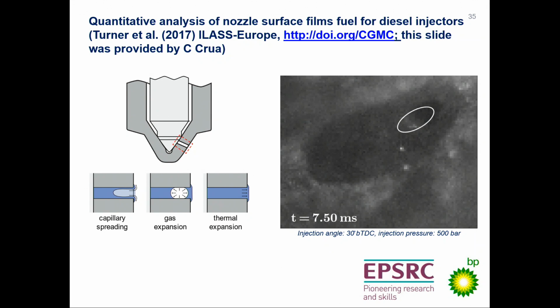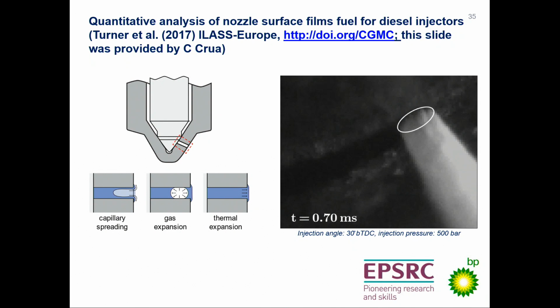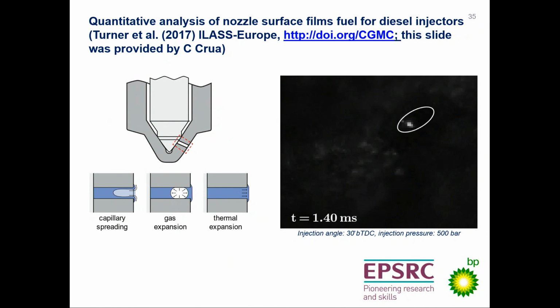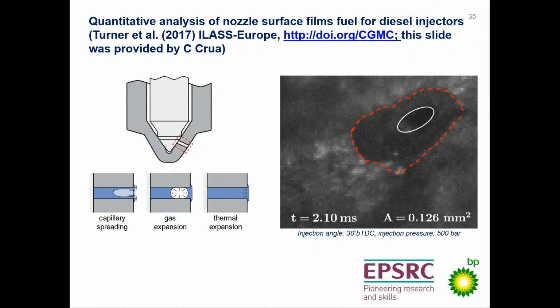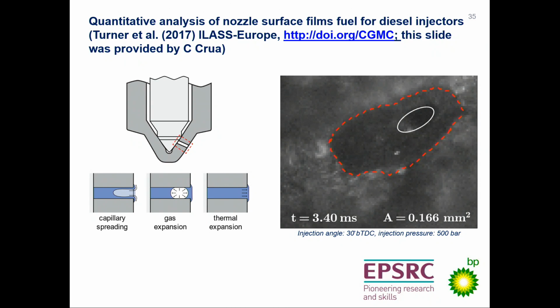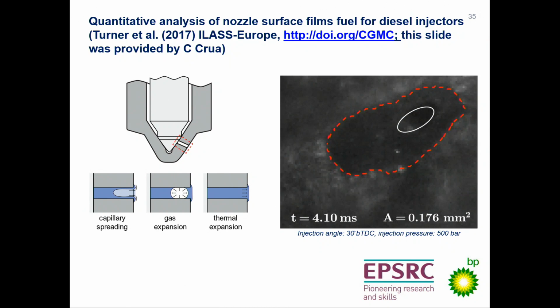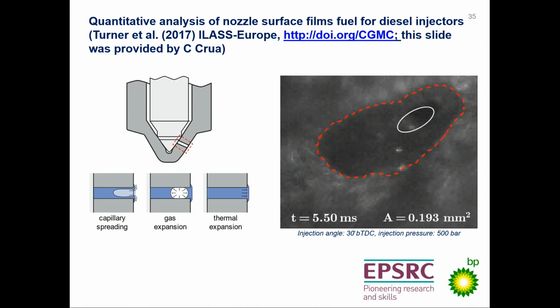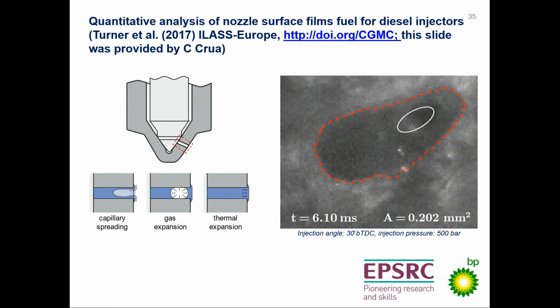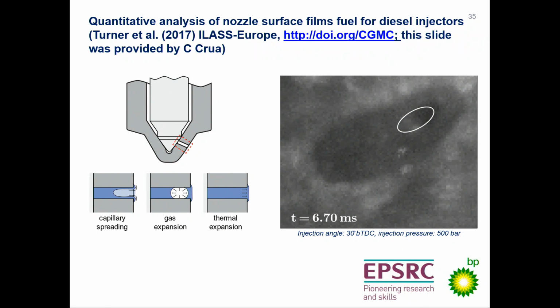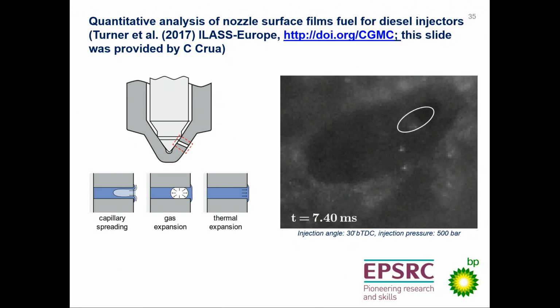This film starts heating and evaporating, and eventually some sort of residuals are formed inside the engines. It is quite essential for understanding the performance of the engines, and the underlying processes which take place there, to be able to model these films. That was the main motivation why this model was developed in the first place, and once it is developed, it can have a much wider range of applications.